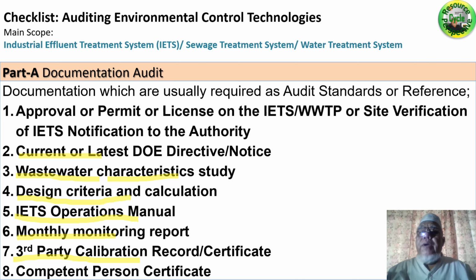Can in-house calibration be accepted? You ask me, yes. They are good, but in this world of standardization, they still need to prove to us legibly that they are certified or competent. So at this juncture, we need to check relevant calibration records of instruments and certification records of calibrating personnel. Okay, good. Let's go to number 8.